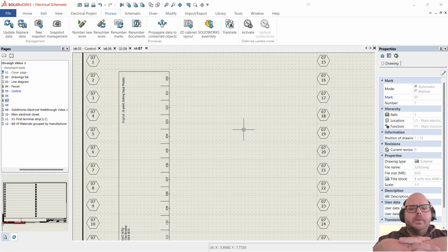It's another built-in manager that SolidWorks Electrical has that makes our bill of materials, and more specifically a separate list of cables, and ordering, planning and configuring our project a whole lot easier. I'm absolutely in love with it. Cables are going to be treated a lot like manufacturer parts. The primary difference is it has a separate manager, so they're treated as cables.